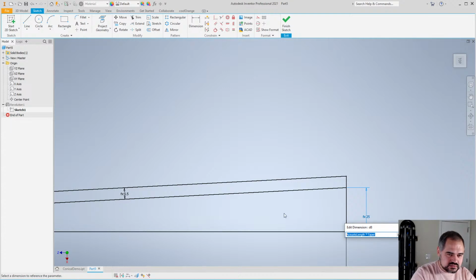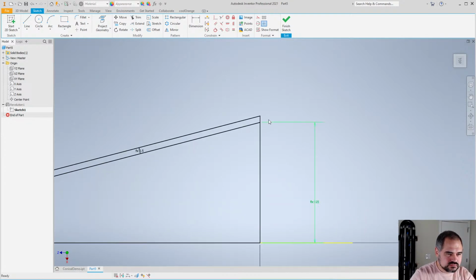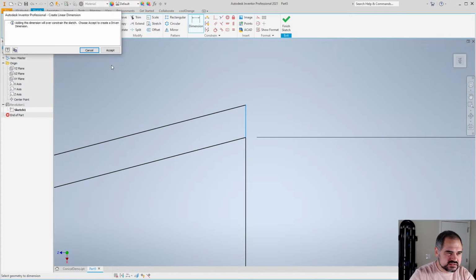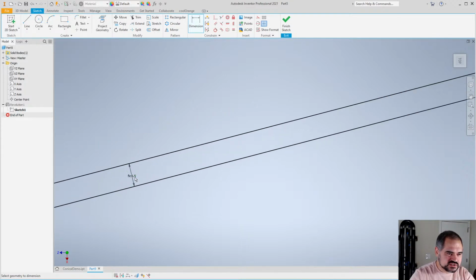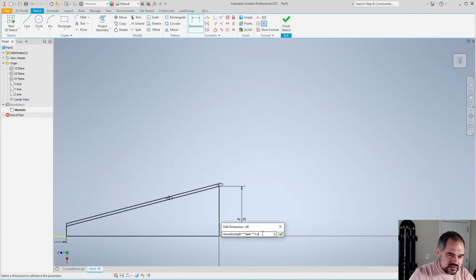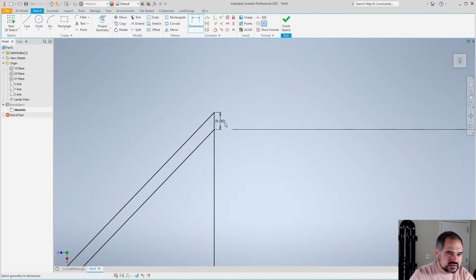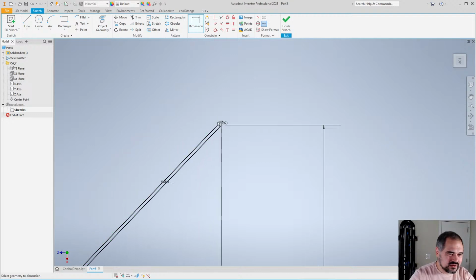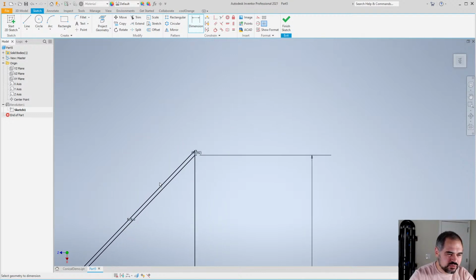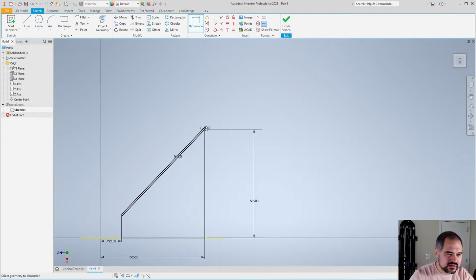If we imagine that the taper was a bit wider, then these dimensions get even further apart. So now we have 6.5 and 6.7. Or multiply the taper by 20, and all of a sudden our wall thickness is 6.5 by one reckoning and 9.2 by another.